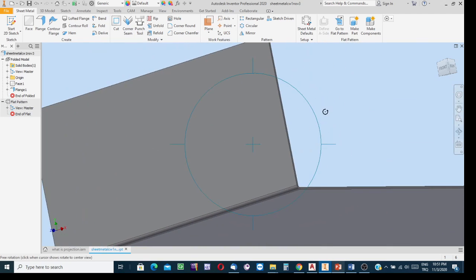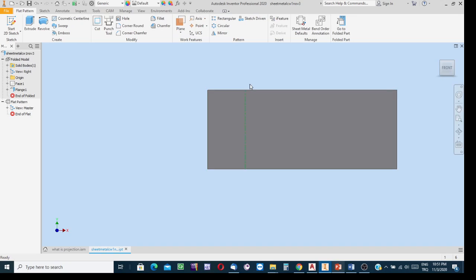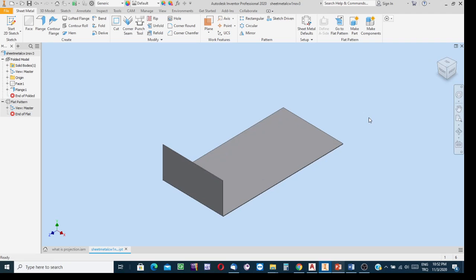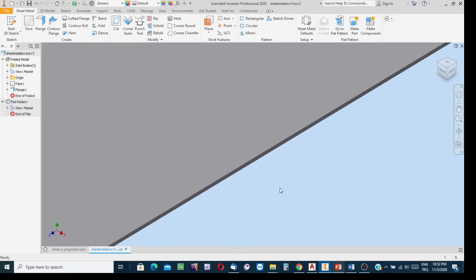When we see the work in this form, clicking on the go to flat pattern button, see the sheet metal work as unfolded over there with the corresponding bending allowance. And then assume that we need to have a folded part, bended part, but it is not to extend from here to there. There is an unfolded part, and between them there is a folded portion. How is it created? How can an intermittent folded part be created?